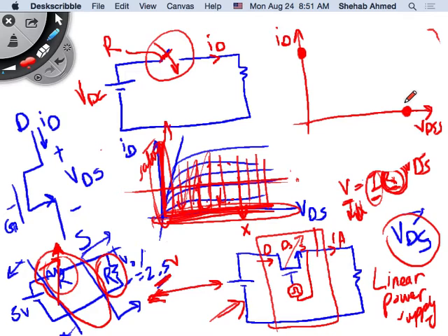You'll find a data sheet for a device that's operating up to 175 degrees C. But at 175 degrees C, we'll look at these characteristics and we'll see that they are recommending that you draw 0 power through the device at 175 degrees C. So what do you do in a downhole application where your ambient is 175? You have to derate and test all the devices and worry about leakage current and worry about these extra things that you would not worry about typically in an application like a computer power supply.